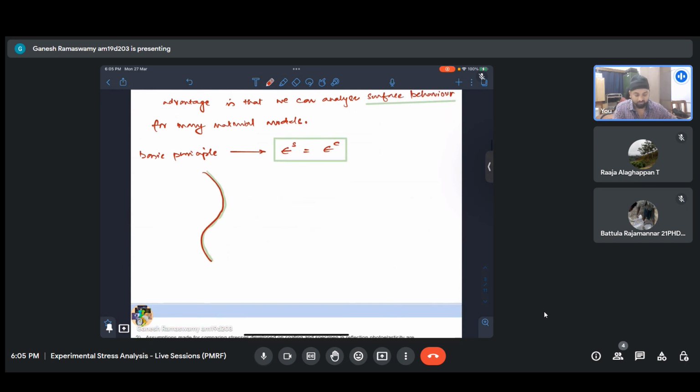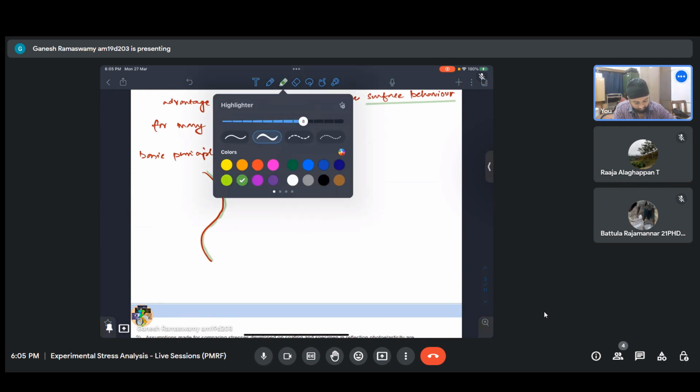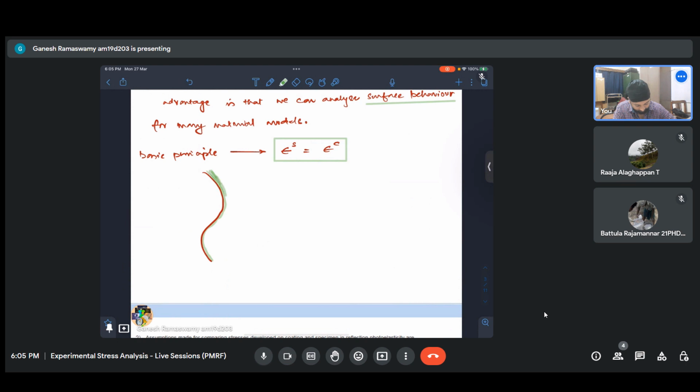This does not quite happen here, in which case we are constrained to have all the setup on one side. Let us say this is the photoelastic coating that has been applied. Ideally, as mentioned in the lecture, I would have a partially translucent mirror that also passes light, and some of the impinging light that gets reflected off this mirror impinges onto the photoelastic coating on the model.